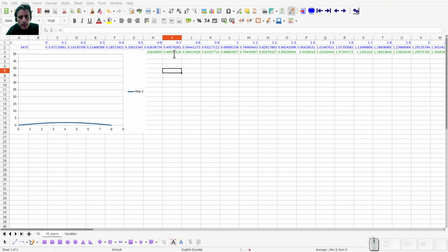But what you do need to define is two variables: iteration underscore src for the source, that's the entire range that will be copied at each iteration, and the area where it will be pasted. You just need the upper left corner with a variable called iteration underscore tgt. Then if you define a variable called iteration max iterations, you need to define a cell with that name. That works in either Excel with the macro for Excel or in LibreOffice. That one will allow you to reset the number of iterations that it runs before it stops.